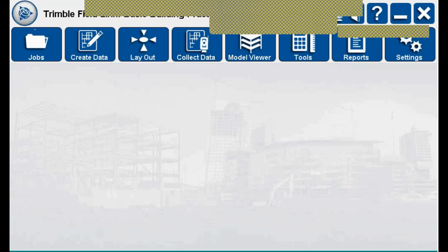Well, again, it all depends on how those units are set. So if those units are not set to unitless, then yeah, you may have to scale it down. And really the only way to tell is to just test the file out and see. But it can start driving you crazy because you'll scale it, so it'll be too big and you'll scale it down by a 12th. And then you'll bring it in and then the tablet will scale it down by another 12th.